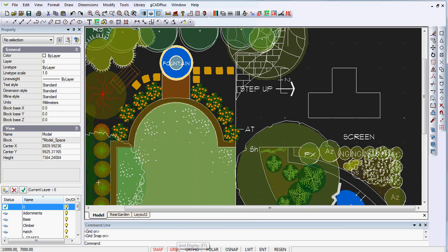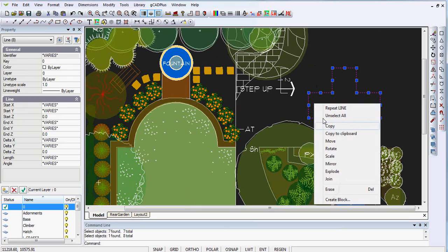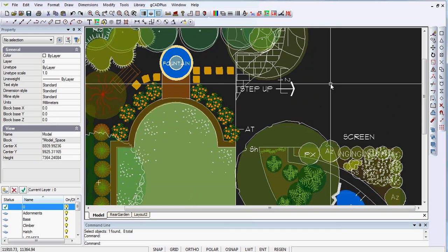You'll notice if you let the cursor hover over them, you can use function keys. Function key F7 will turn the grid off. So if I press F7 now, the grid goes and the tab returns to a blank tab. F9 takes snap off. So now we're back to the normal situation. One more, right click and erase. So I don't think you necessarily have to work and experiment with things on the tab settings at this stage, but you do need to be aware of them.